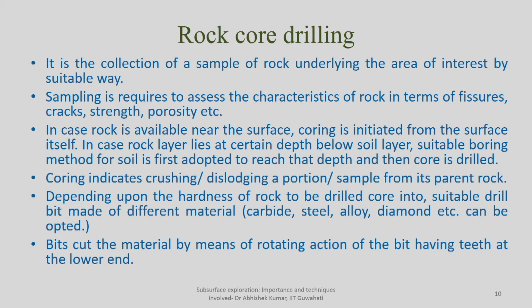Now we go for rock core sampling. So what is rock core sampling? It is a process of collecting rock samples which underlie the area of interest by a suitable method. Sampling is required so that you can collect the rock which is available at that particular depth, which may not be actually accessible to you in its natural condition. You bring it onto the surface and you characterize the rock in terms of fissures, cracks, strength, and porosity also.